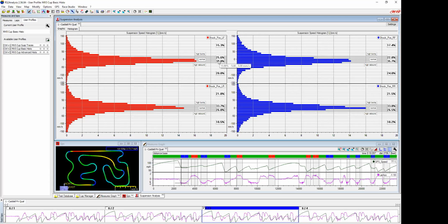What we probably would want to do is give it a little bit more low speed rebound control, where you would then get this number down, where it's not just maybe some wheel hop or some chatter in this front tire. And we would probably want to allow it to be a little bit more here in the higher speed stuff. When we change that number, this one transitions. Of course, we're talking low speed, high speed. There isn't a definite wall there. There is some crossover, obviously. But that's a basic idea of how to begin to read these numbers, okay?